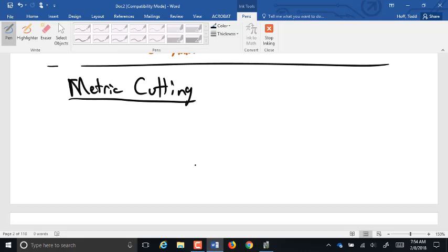If you send it out to be done at a foreign place, you've got to use different tooling and all that stuff. Having everything done in metric meant it was the same tooling, all one drawing, you didn't have to double label anything. And because you weren't converting units, there weren't round-off errors, so the quality of the parts meshing was a lot better. They had a lot fewer rejects because parts didn't want to mesh.